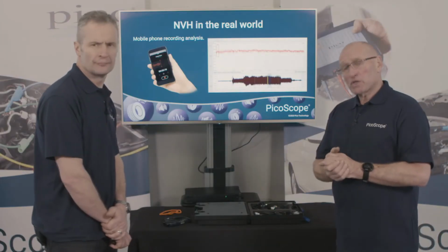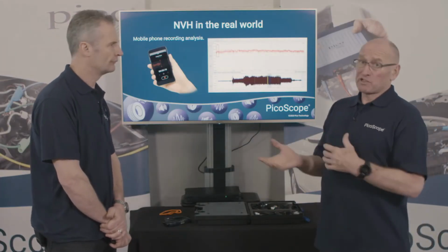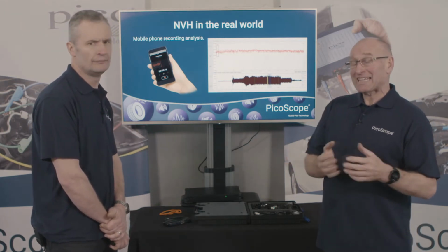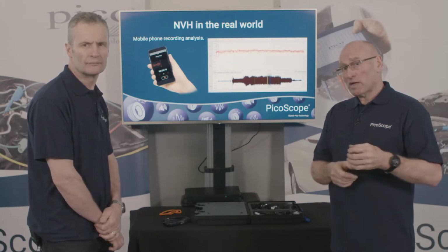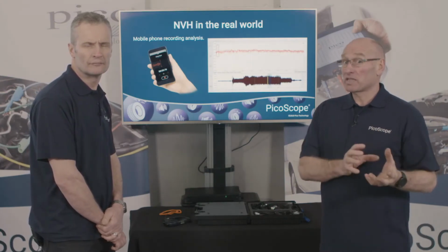I've often said when using NVH, let's assume, as Steve has just suggested, that we actually don't put any data in whatsoever. Apply the common sense rule that we can almost predict what sort of frequencies the engine will be operating at, and, let's assume the final drive's around 4:1, what sort of frequencies the tyres and the wheels are going to operate at. Anything between those two figures will be related to transmission. So even with what I call common sense application, we can pretty much predict what area we're going to then focus on next.